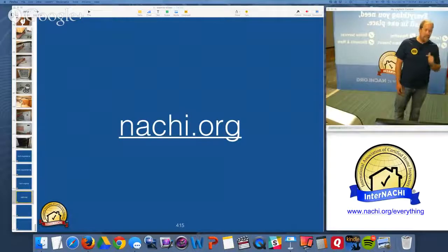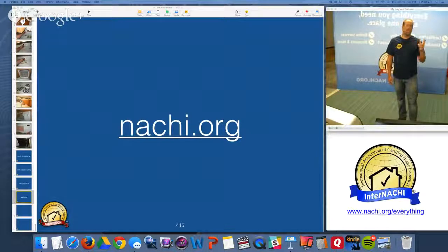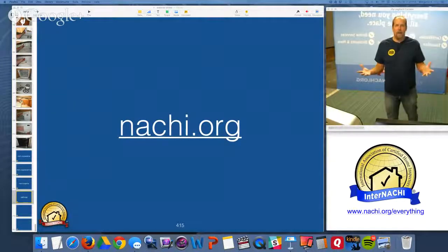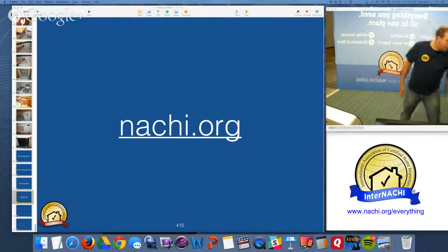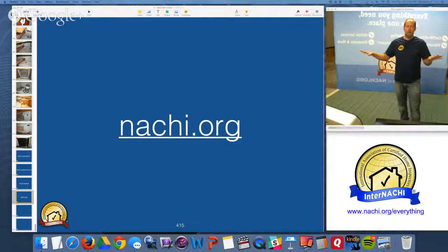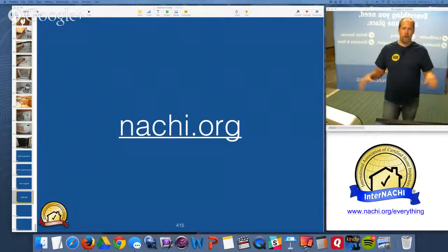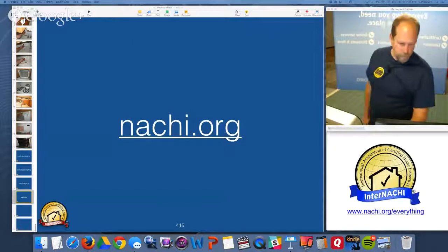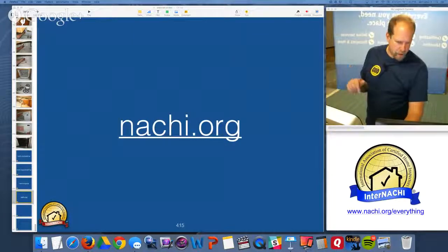The AFCIs, if it's a vacant home, I'm going to test them. The breakers, I'm popping the AFCI breakers at the panel. They're supposed to be tested that way. It's okay. The other way to test them is through one of these testers, and you can do that from a bedroom, for example. But I want to make sure that I have permission to do so. And AFCI, it's difficult. If you can test it, test it. But I would ask for permission first, just to be safe.